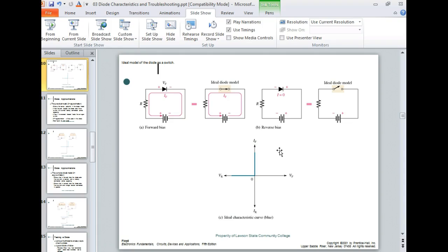So what we'll do is we'll show you how to wire a potentiometer. We're going to use a potentiometer. Y'all know what we use the potentiometer for? To control what? A voltage. Not regulate, control the voltage. They don't regulate it at all. But if I've got a 10 volt power supply and I hook up a pot, I can get anywhere from 0 to 10 volts out of the wiper of the pot. So we'll have to do that with our power supplies.